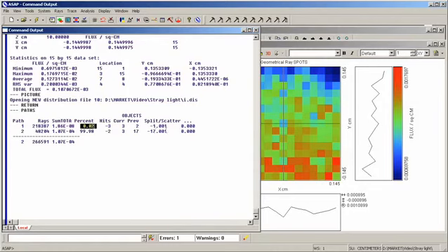Similarly, path number 2 consists of all rays that were scattered from object 17. They're currently in object 3, the detector. They were previously in object 17, which is the inner conical baffle, and they had a total of 2 objects hit altogether. This path consists of 99.98% of all of the possible stray light.